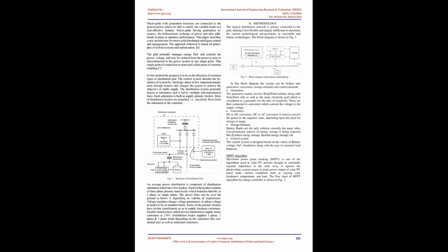2. For the communication-assisted dual-setting relay protection scheme, authors propose the use of dual-setting directional overcurrent relays which are capable of operating in both forward and reverse directions along with various settings and with lower bandwidth communication in order to maintain proper coordination. The problem is formulated as a nonlinear constrained programming problem where the relay settings are optimally determined to minimize the overall relay operating time for primary and backup operation.